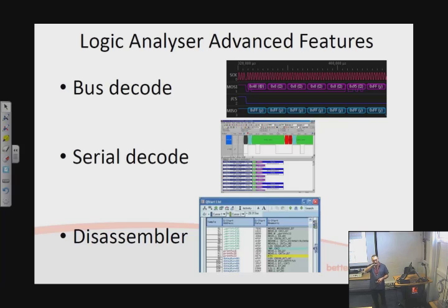But most of the time, if that's a bus, we will want to consider it as a 4-bit bus, at which point the logic analyzer is quite capable of merging those 4 signals and, instead of the individual 0s and 1s, displaying any number from 0 to 15, or F hex. That's very powerful. There's an example of it in this slide here, so have a look at that.